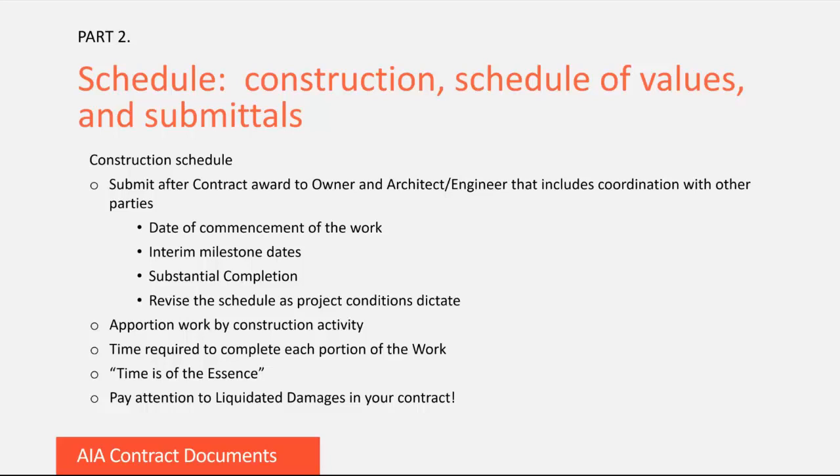It's also helpful for their internal coordination, especially in a manufacturing or industrial facility where the owner's employees need to shut down certain lines for the contractor to perform work and make tie-ins. Often with these, the owner's personnel have to plan days in advance of a shutdown to reroute their system's activities. A detailed schedule also aids the contractor in organizing its work and makes it easier to justify progress payments when the owner inquires about actual steps of the work that are complete. Also, if there is a CMA on the project, they are definitely going to require a detailed schedule breakdown.